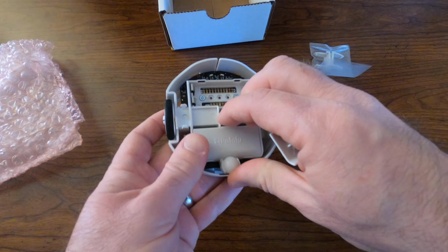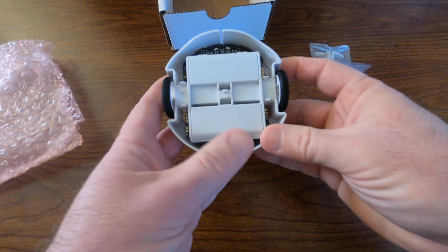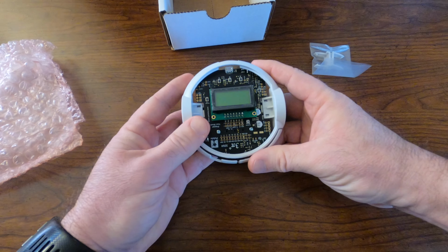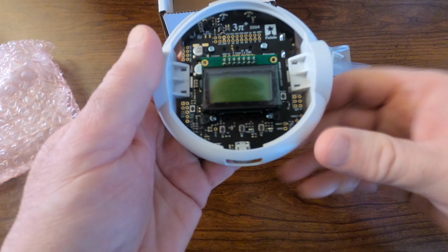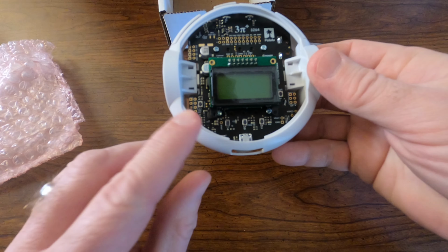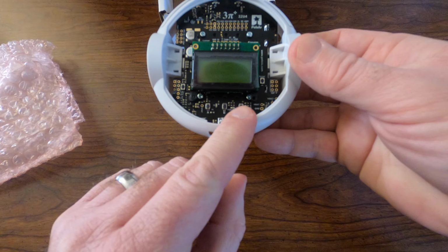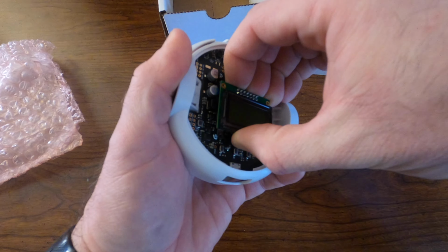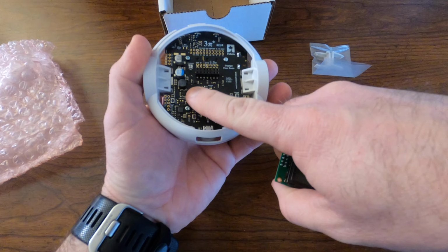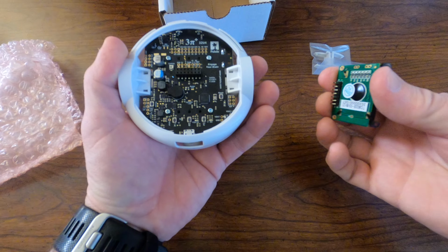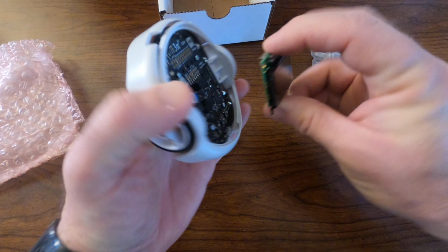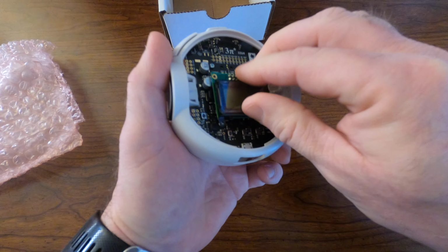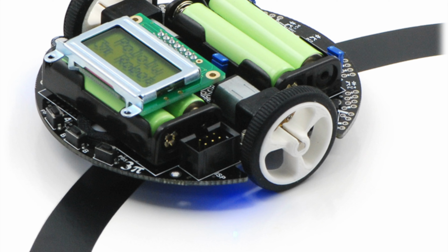They're AAA in size. This is a differential drive robot, so we have our two drive wheels and a caster wheel. On the top here we have an LCD screen. We're actually going to be probably removing that, but I'm going to use it for this demo. We have a power switch on one side, reset, and 3 buttons below, A, B, and C. I'm going to remove the LCD screen here momentarily to show that there's a buzzer underneath here, so we can use that to play sounds. And we're also going to use that jumper header to attach some hardware. So I'm going to look at adding servos and ultrasonics on top.